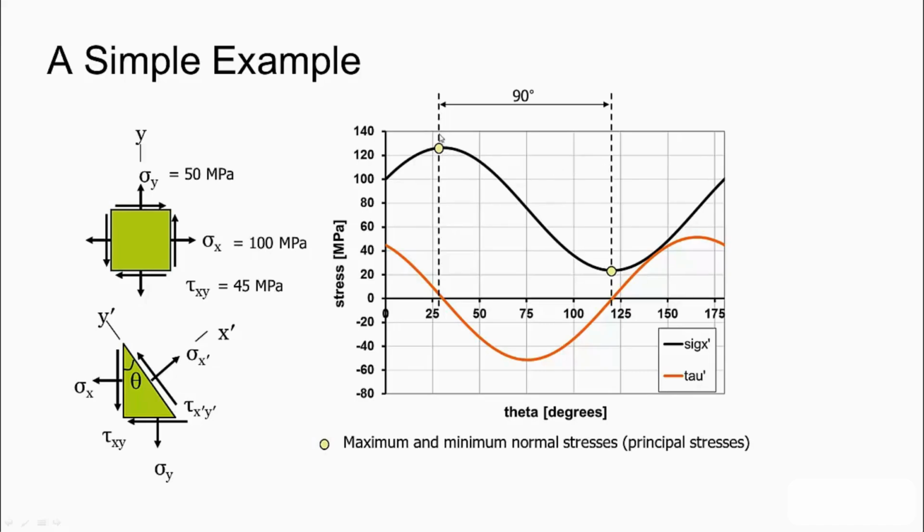So it is a normal stress state that acts on two orthogonal planes. Furthermore, they occur where the shear stress is 0. So the principal stresses will act on a set of orthogonal planes oriented in such a way that there are 0 shear stresses. Now if we look at the shear stresses, we also get a local minimum and maximum, and we see that they are also separated by 90 degrees, but they are also separated from the plane of principal stresses by 45 degrees.